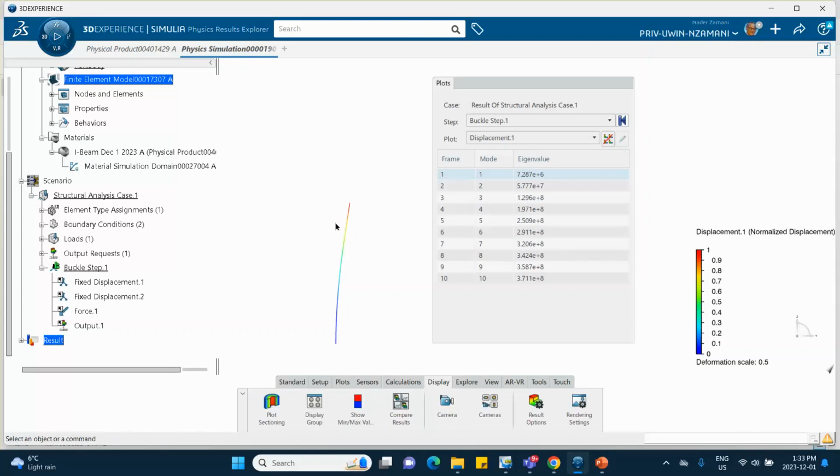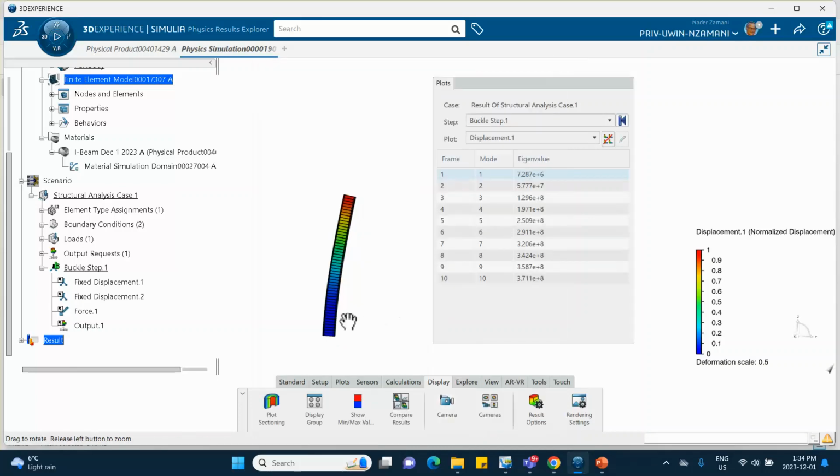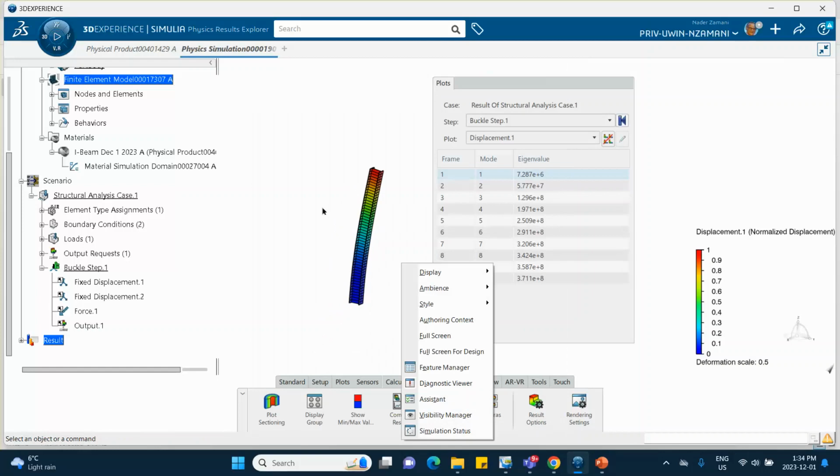In the event that you want to see the beam in 3D, not as just a straight line, what you need to do is you double click on this contour, any one of these, doesn't matter, the first one, for example, and you select this third tab up here, right there, rendering. Okay, now I don't want line. If you pull it down and say profile, or profile and line, let me try profile, and then we say okay, you can see that it also shows it to you in 3D.